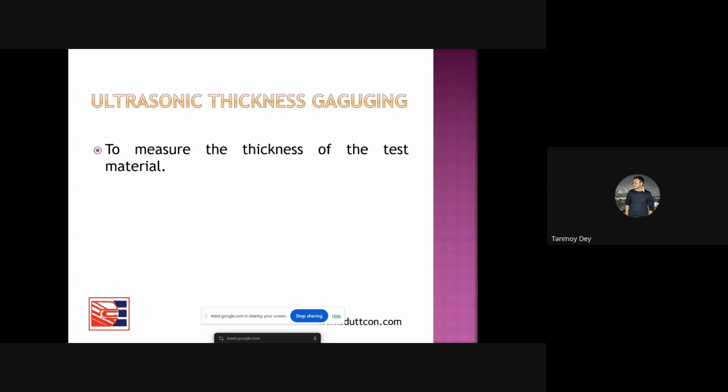As I've already told, in any power sector or any other boiler, we are testing this. To avoid any bursting of a pipe, thickness is measured through ultrasound. In my first slide, I tried to make you understand how sound gives an idea of the thickness. So this is the principle through which we can measure the thickness of the wall of a pipe.